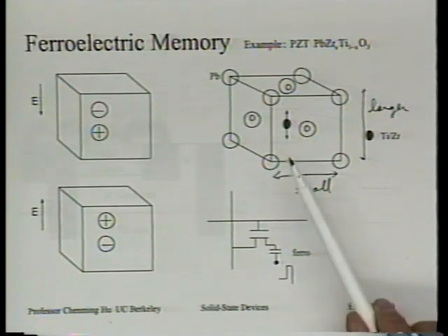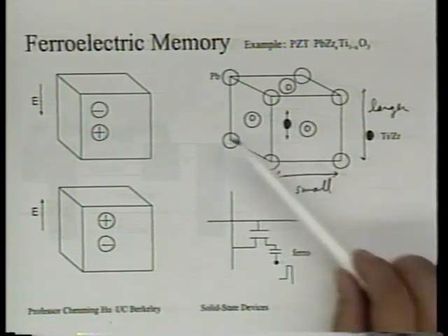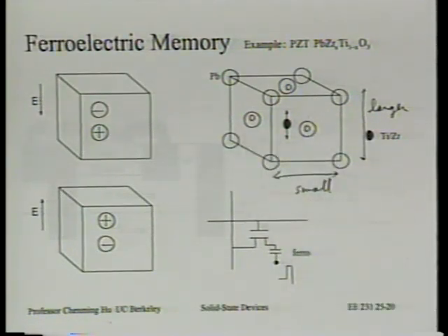If you are that black ball, would you like to stay exactly in the center of this box? Is that where you have most room? Or could it actually be slightly above that center plane or slightly below the center plane? You see, the fact is at the center plane there are 4 oxygen atoms. So if you go a little bit above that plane, or a little bit lower than that plane, actually it's a lower energy state. And that's the mechanism for the memory.